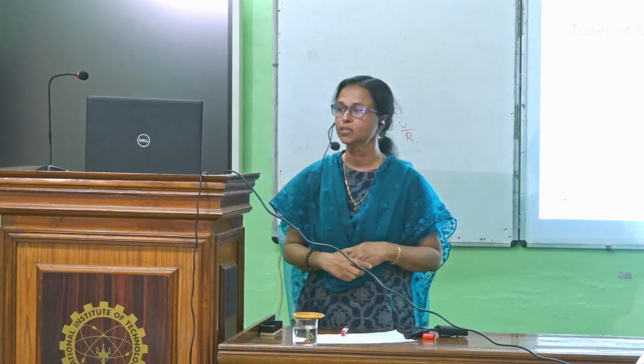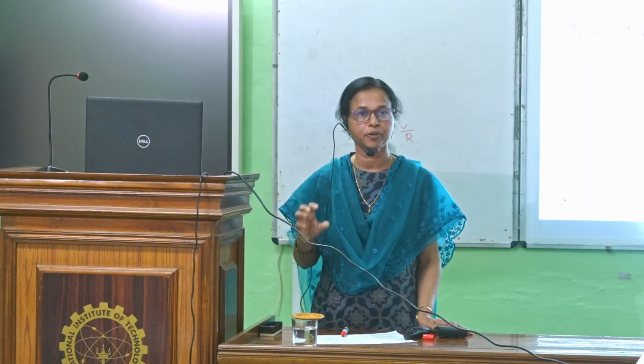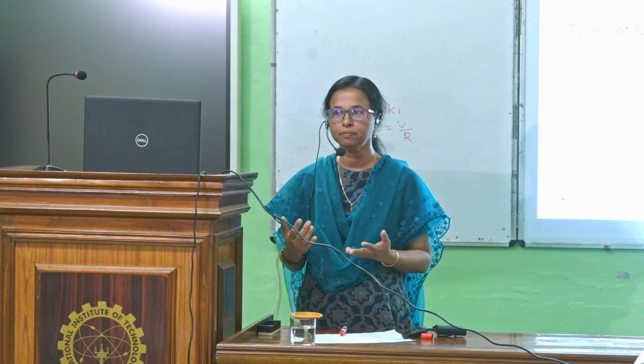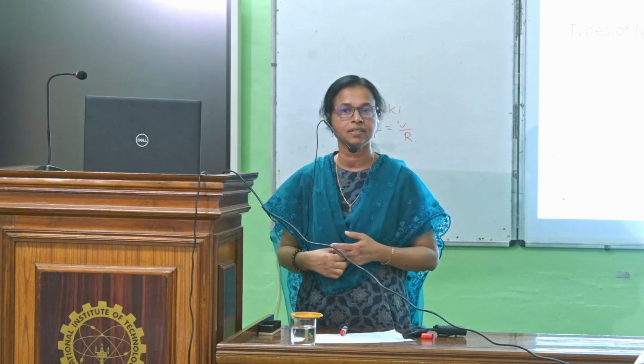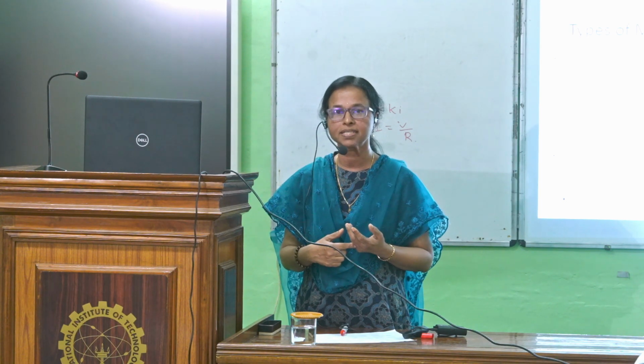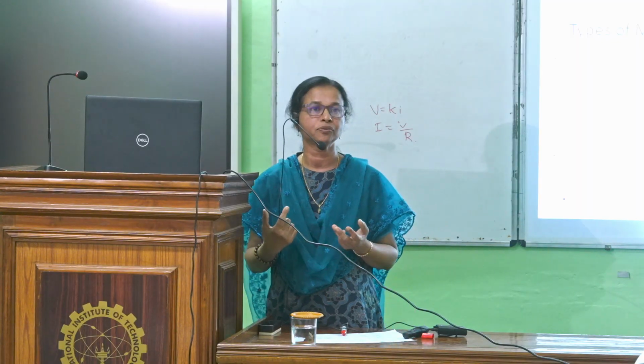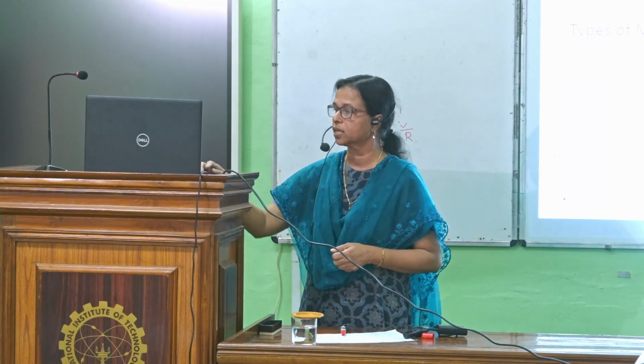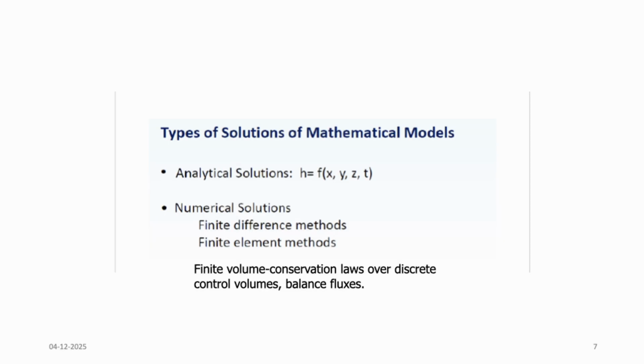What are event-based and continuous models? For a particular event, you are simulating; the other one is continuous. Event-based models have a lot of applications. What are the applications? If you want to develop a design storm. What about the continuous model? Suppose you want to develop reservoir operation, this you need continuous data, so you can go for continuous models. Based on solution techniques, mathematical models can be classified into analytical and numerical methods.